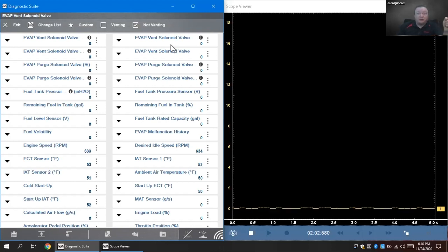And that's where we're going to leave off this week. Is we tested the solenoid. Solenoid's no good. We verified the solenoid's no good because I have power in and I have no power getting out the other side. We could also, suppose, do a resistance test on it as well. But in this case, no voltage in, no voltage out. That indicates it's bad. And that's where we're going to leave off this week and pick up next week, where we're going to talk about ordering the part and verifying the repair.